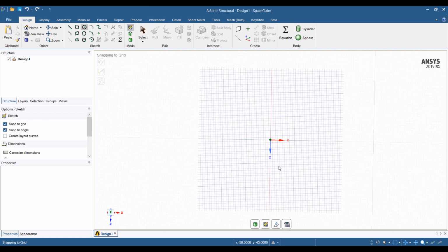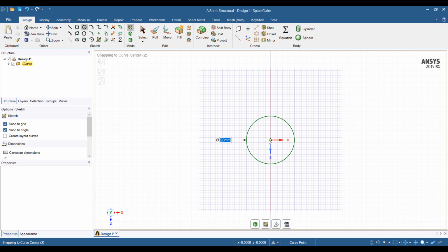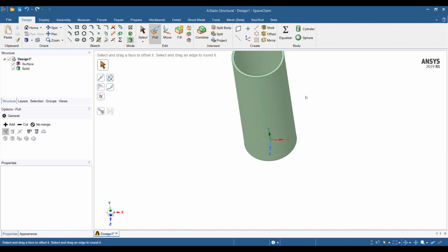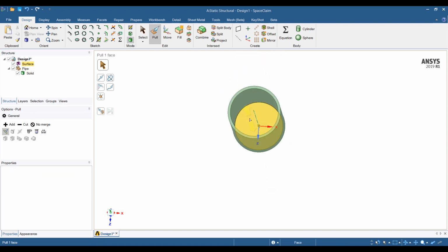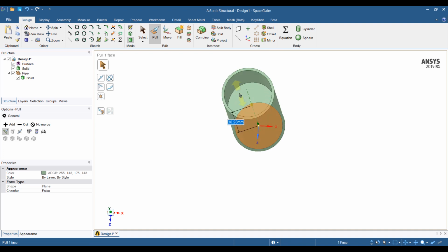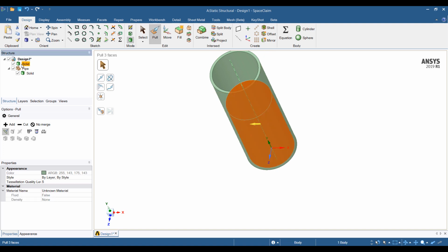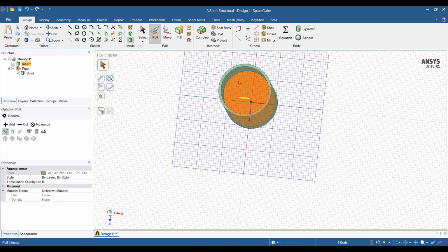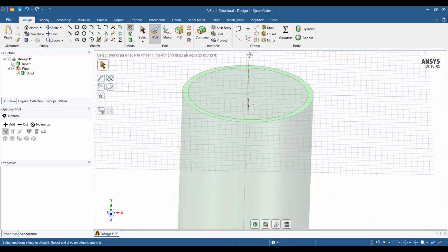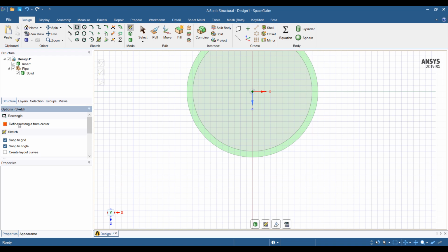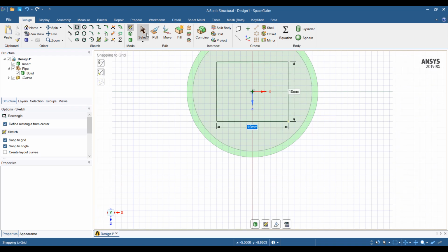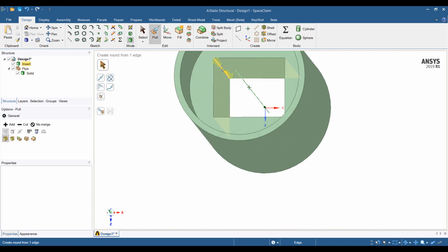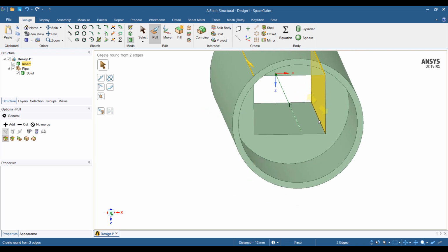So I'm going to start by creating the geometry. Let's do a 20 millimeter pipe by 22. We'll make it about this long, and I'll call this one the pipe. The interior part, we'll pull on this, maybe not quite as far, and we'll call this one the insert. Okay, if we just do a solid insert, it's kind of boring, so we can put some changes on this model. So let's cut a hole into it. And we will add in some fillets to relieve the stress that develops in these corners.